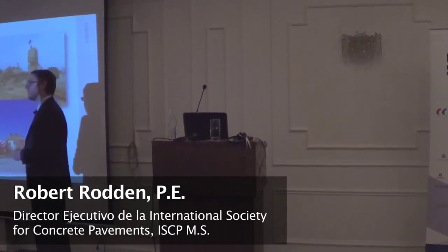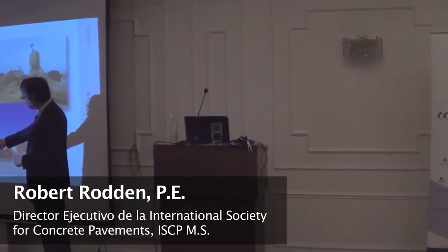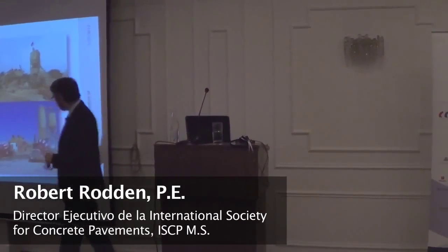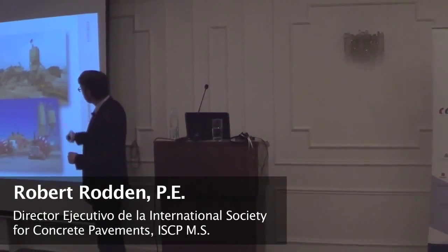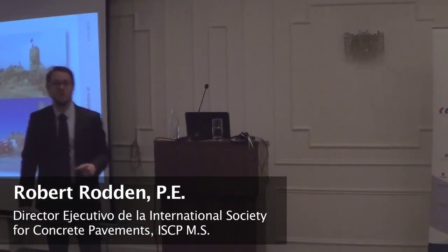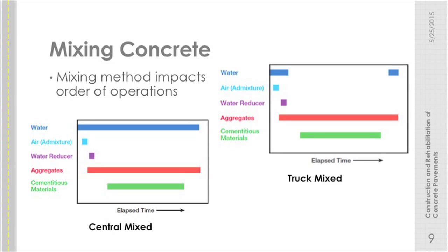If we're close to a city, we can use truck mixed or ready mixed concrete, where the trucks themselves are doing the mixing of the concrete. But you can only transport that so far. And there are differences in the mixing operations themselves between truck mixed and central mixed.